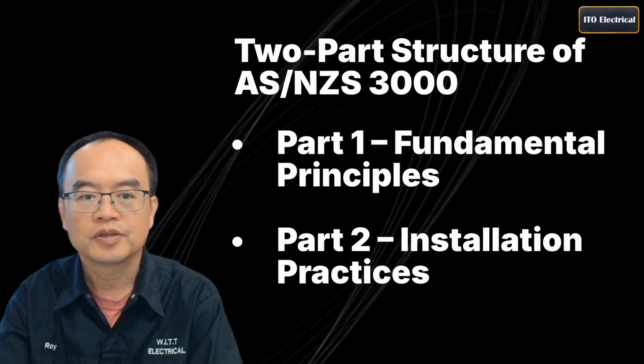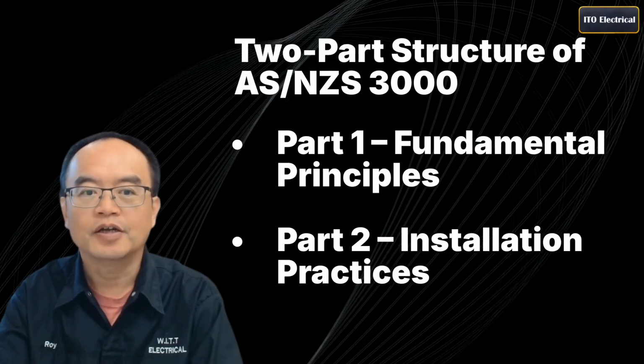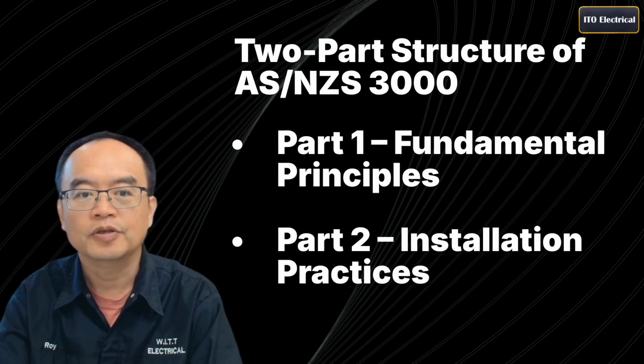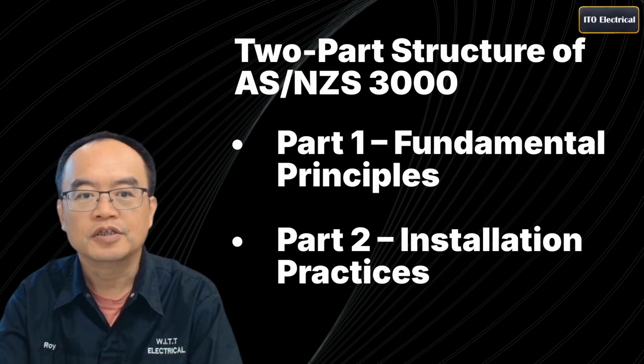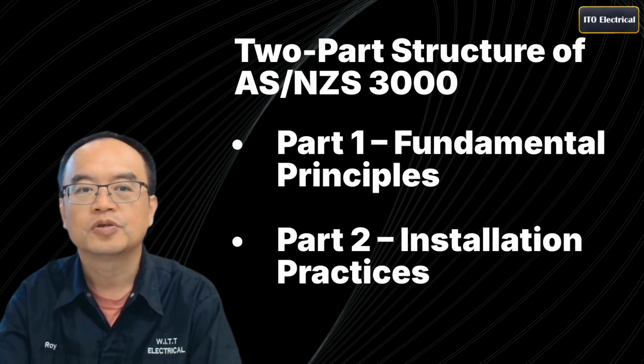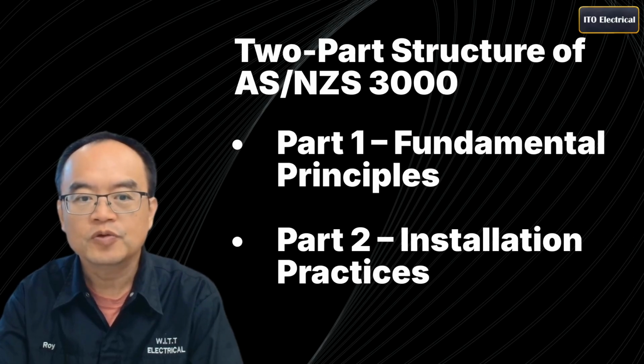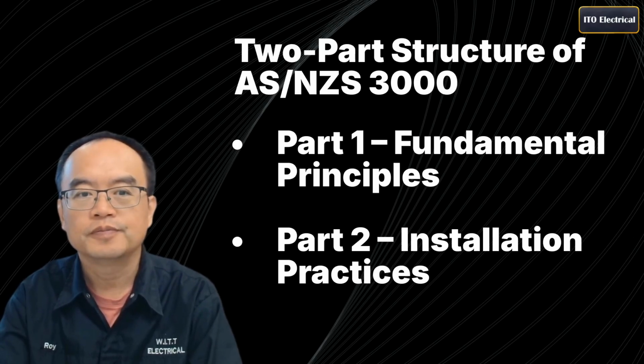AS/NZS 3000 is split into two main parts. Part 1 outlines the core safety principles. These are the essential high-level requirements. Part 2 gives specific step-by-step instructions, deemed-to-comply methods to meet those principles. If you follow Part 2 exactly, you automatically satisfy Part 1. If you choose an alternative, you must prove it's equally safe.